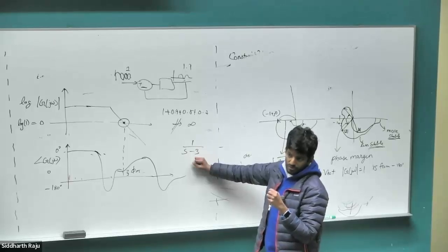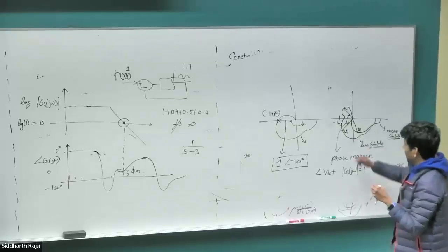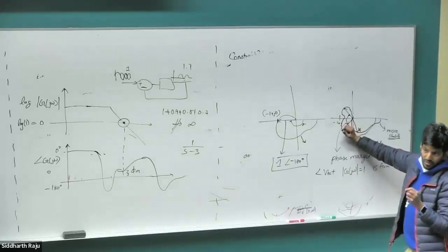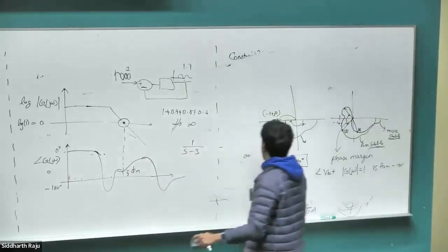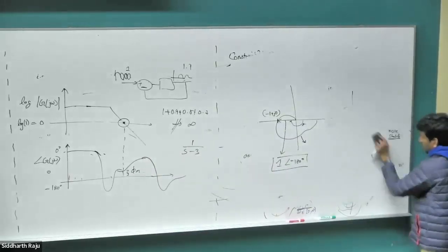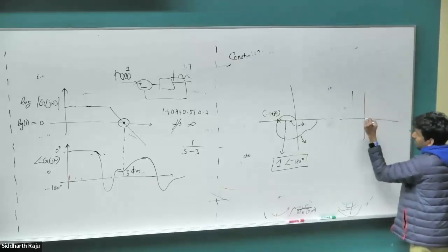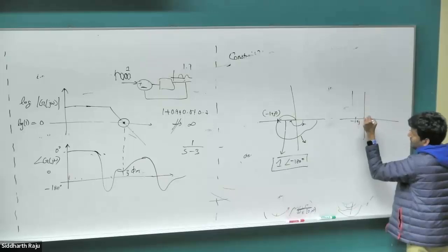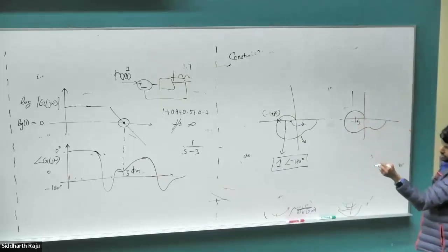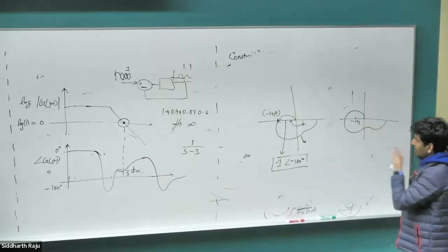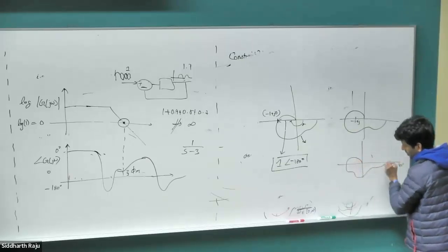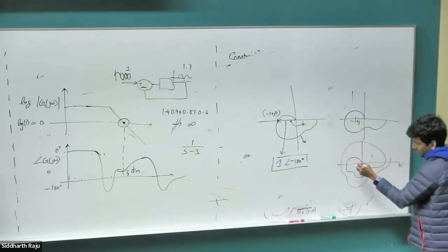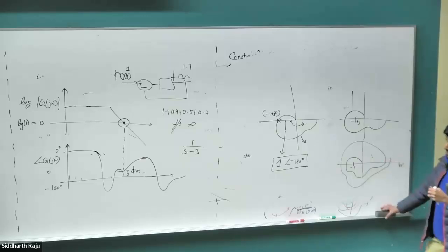You said if it encircles the -1 point, all you're doing is growing that. If it was a single encirclement, right? If I have a double pole, it will be a double encirclement. Oh, that's a good visualization. So let's say we start off like this, that would be the case of a single pole, because it's just a single encirclement. And then of course you can scale it up and down. Case of a double pole, I think so. Yeah, you should be able to do that. Right, in this case too, you shrink all of this effectively, you should be able to make it stable.